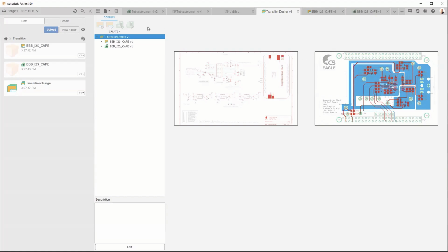Okay, this document is also going to be responsible for linking your 3D model of your PCB. So Jorge, you created the project, and in the project you created the electronic document, and then from the electronic document you've referenced that schematic, and then you reference that board in the same electronic document. So what's going to happen now is that that board and that schematic are going to be associated. Is that going to control now that the board and the schematic kind of keep annotation between them from this point on? Correct. This is going to be the glue that holds them together.